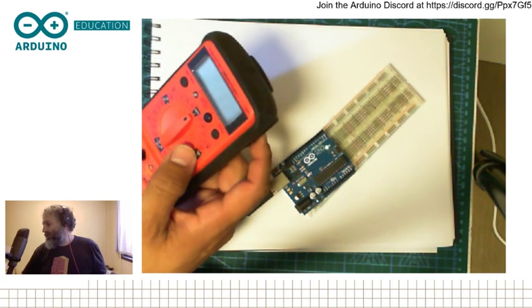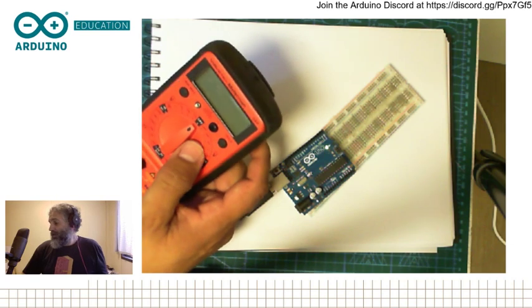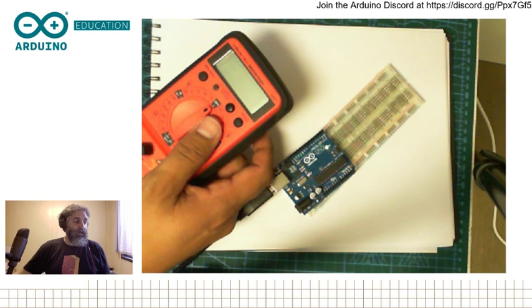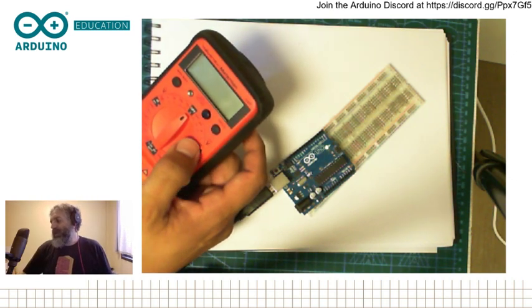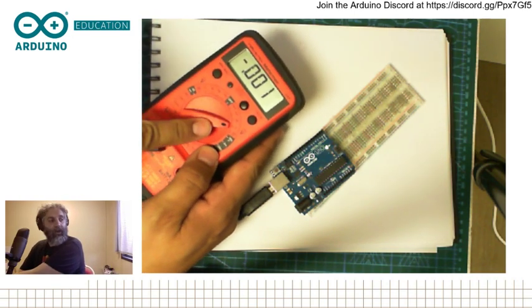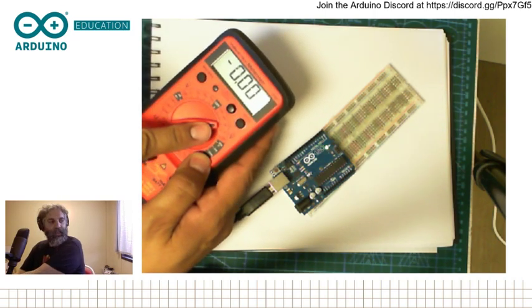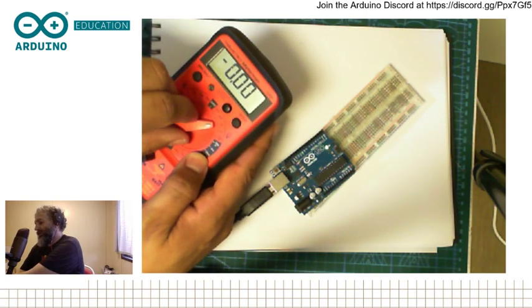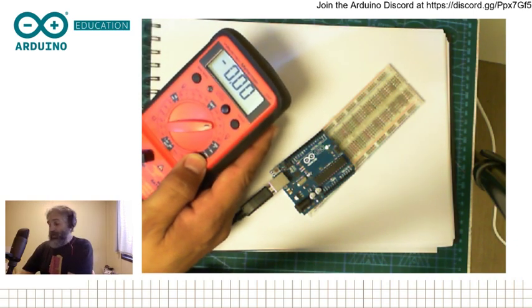So for example, in voltage, I see here there are values of 200 m, which is millivolts, 2, 20, 200, and 1000. This means that if I want to measure direct voltage, and I know it's going to be up to 2 volts, I should put it on that part of the scale. If I want to measure up to 20 volts, I should go to the next point of the scale, and so on and so forth. It's very important that you respect that, because otherwise the multimeter is going to show that it is overloaded, and you will not read anything.